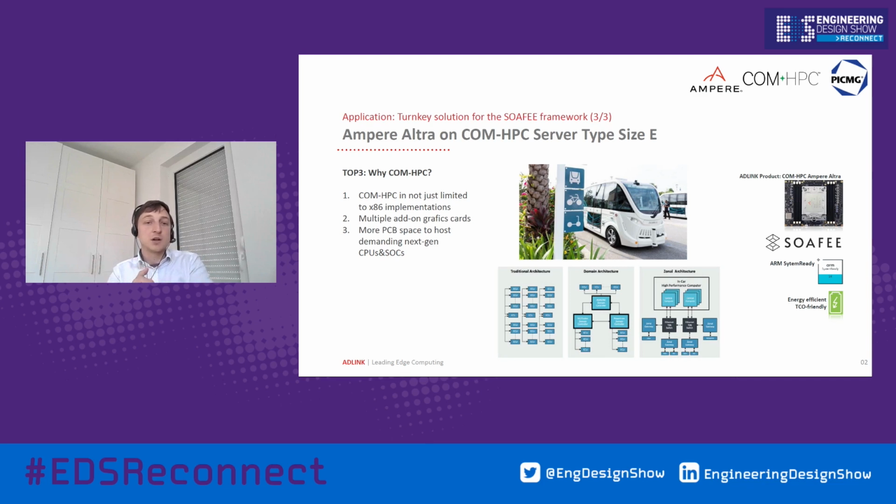Most production cars today have multiple small-cell fixed functional ECUs on board. The domain architecture, in contrast, is already consolidating a few ECUs. Due to the availability of powerful heterogeneous systems on chips based on ARM computing, they try to consolidate the workloads into not so many ECUs anymore.